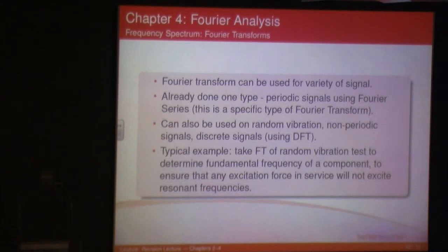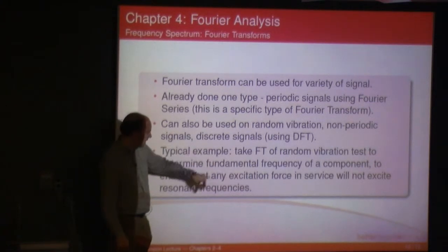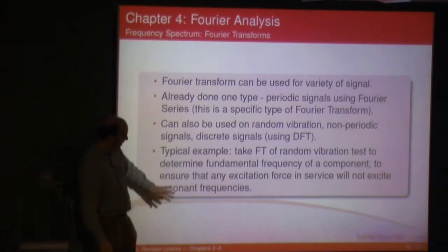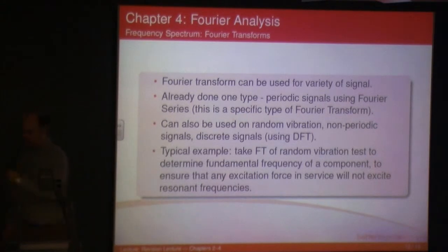Like I said, you can shake it randomly and it will get a time domain result. Take the Fourier transform of that, you get your natural frequencies. And what you want to do is make sure your natural frequencies don't coincide with the oscillation that's being excited, okay. So like I said, with the helicopter example, you want to make sure the natural frequencies of that structure won't be excited by the oscillation of the rotors.